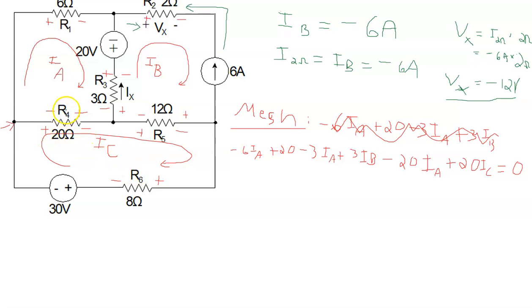Then we have to take into account 2 mesh currents through there, so 2 terms in the mesh equation for that resistor, 2 terms for all shared resistors. The mesh we're writing it for will be negative, the other one will be positive. Again, you do mesh analysis the same way every time. You get the similarities, which makes it easy for you.